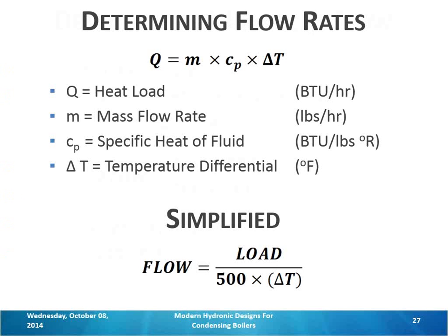So in this selection, we need 180-degree water when it's 0 degrees outside, and we need 100-degree water when it's 50 degrees outside. And that's the supply. So our return temperature should be 30 degrees less than this throughout the year, if we can maintain that delta T.